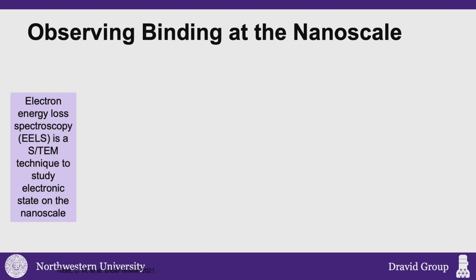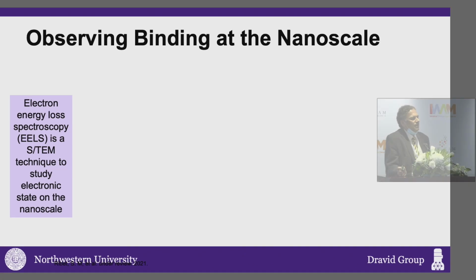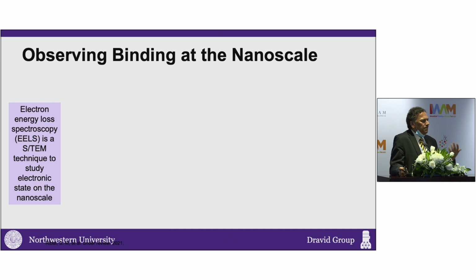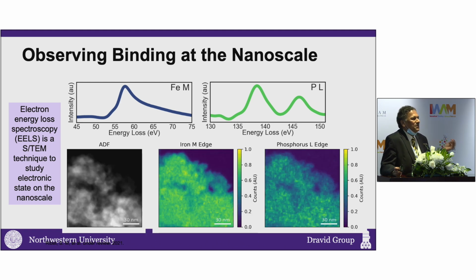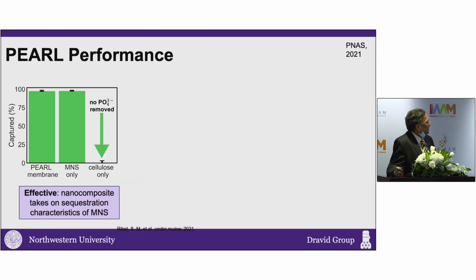We also look at association. So how do we know that the actual nanostructures are doing the job that they are? And remember, there's a lot of precedence of using iron-based systems for phosphate recovery, but they are done in a very haphazard way, which is using powder, and it's impossible to manage powders in massive quantities, right? But having a sponge as a platform, you don't have to worry about spillage or anything. So there's less than 0.2% is recovered. And then here is the energy loss spectroscopy, where you look at iron and phosphorus association, so you know exactly why and how these things are working.